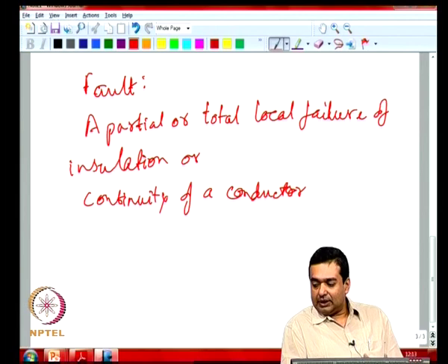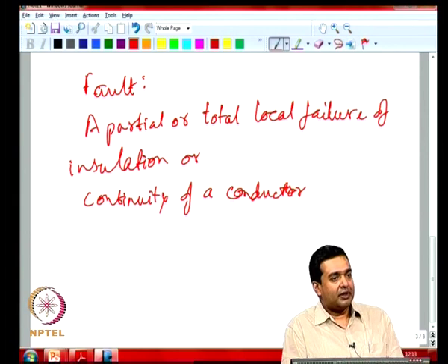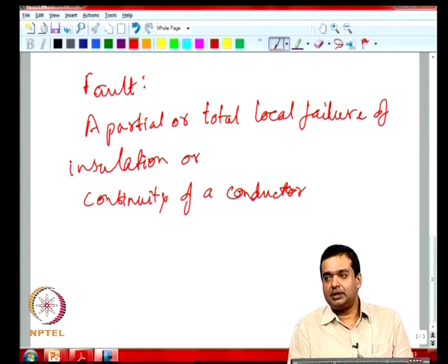If you look at the nature of what happens when you have a fault, say you have arcing of insulators, ceramic insulators on a line, if arcing starts on a line, essentially to stop the arcing you have to disconnect or de-energize the line by opening an upstream breaker. So, you can think of it as stopping fuel supply to that particular fault point.